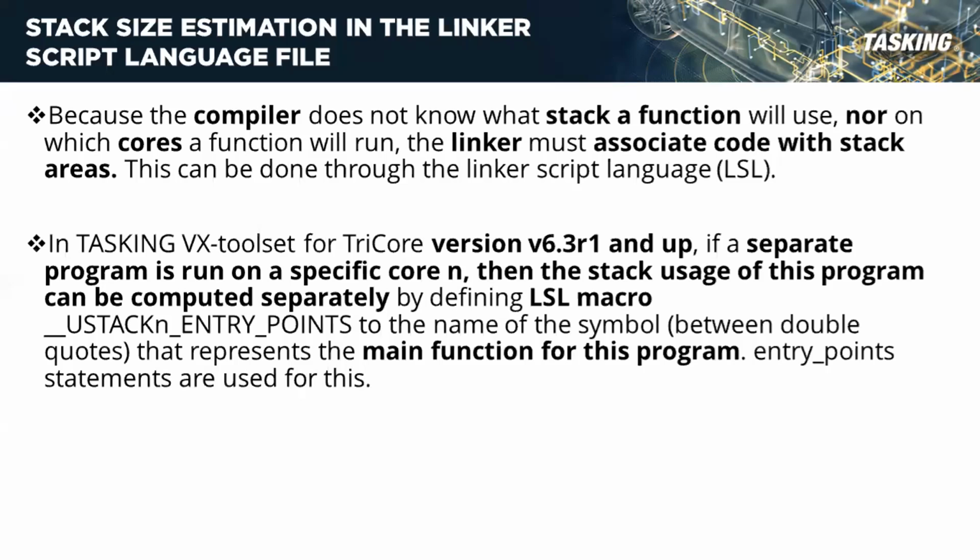Let's have a look here at the LSL file, or the linker script file. The linker script file is a configuration file that gives instructions to the linker for the functions and for the stacks. The compiler itself is really not aware of the stacks, and it's not aware of which function will run on which core.